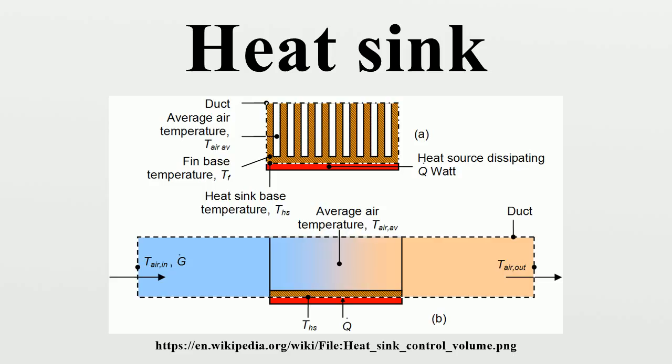A heat sink is designed to maximize its surface area in contact with the cooling medium surrounding it, such as the air. Air velocity, choice of material, protrusion design and surface treatment are factors that affect the performance of a heat sink. Heat sink attachment methods and thermal interface materials also affect the die temperature of the integrated circuit.